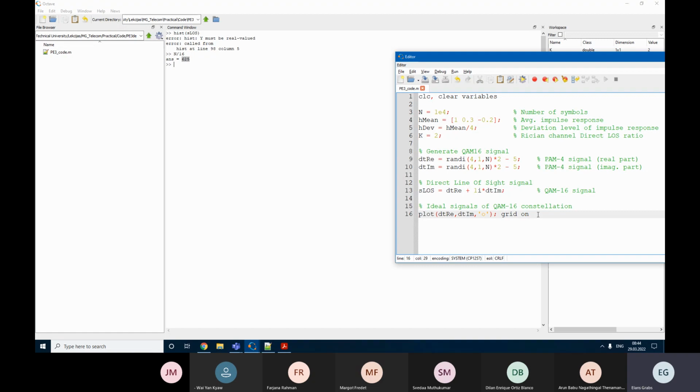So that means that each of these numbers is equally possible, right? Okay, so what we want to do now is to avoid plotting all this unnecessary data and display only unique points. For that we need to calculate our constellation. So let us find the QAM-16 ideal constellation, which we might need later to actually decode or detect the signal, right? So this is map, and accordingly we are going to use the function called unique that finds only unique combinations of these signals.